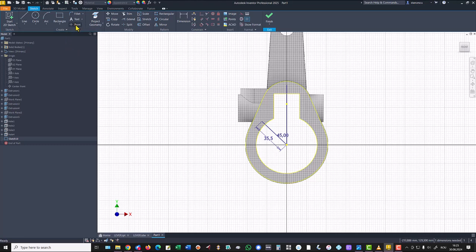We place two new entities, 2 points, then we apply the circular pattern for this point about this center, not 6 but 4.